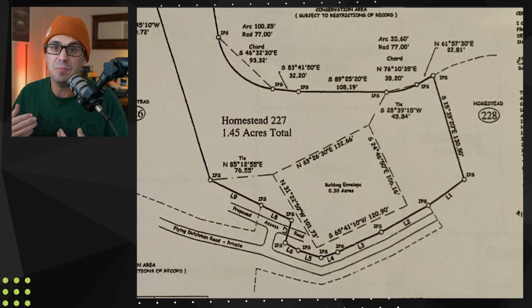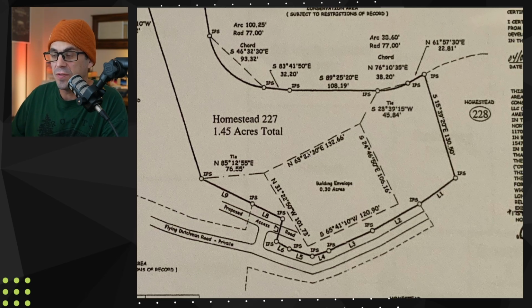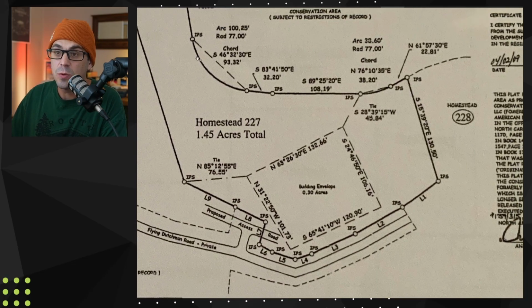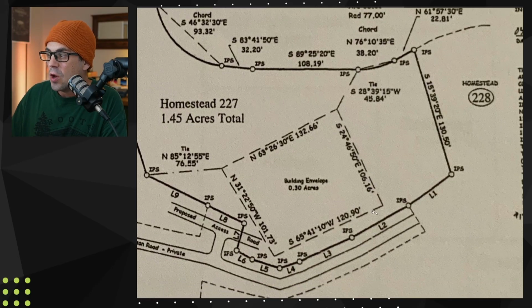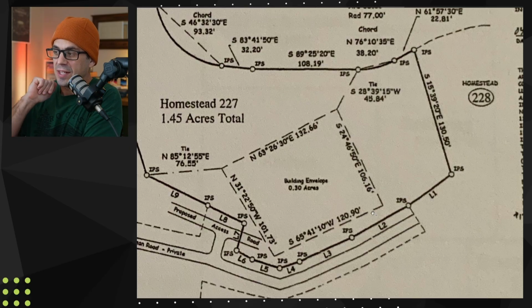This is how drafters, designers, architects, people like me would know how big your floor plan can be to even start anything. So here's an example of a boundary survey. The information you need to know here is pretty simple. What we're needing to read, you have these solid lines which show your property. These dashed lines are then what the county has really deemed buildable area. Maybe it's through easements, maybe it's through required setback lines. Sometimes a lot of things like this are on here.